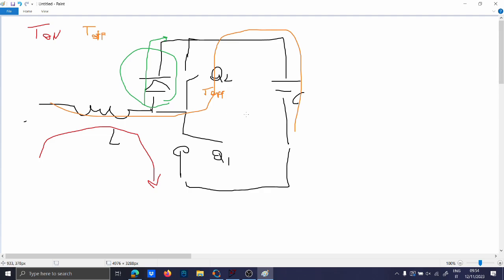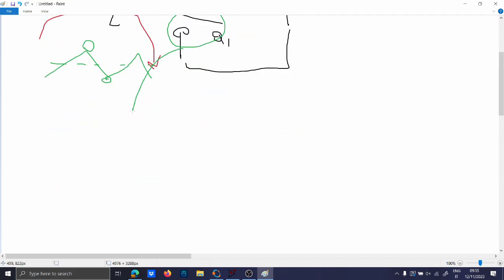To estimate the switching losses, you first need all the parameters that you actually need for the current, and so the waveforms are like this. And you need the inductor peak current, the RMS of the inductor, and also the minimum current of the inductor. Estimating the switching losses of these two switches is important because you then plug the losses